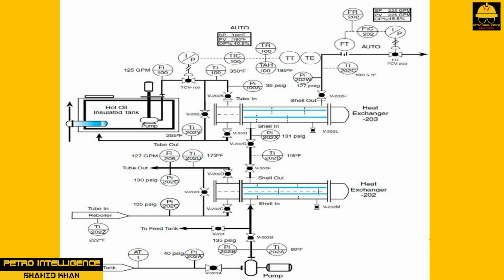15. Ensure flow from reboiler to EX202 to tank farm is moving and pressure instrument readings are normal. 16. Increase FIC 202 to 225 GPM and let heat transfer system line out. 17. Visually inspect all equipment, piping, and instrumentation and take initial run readings.